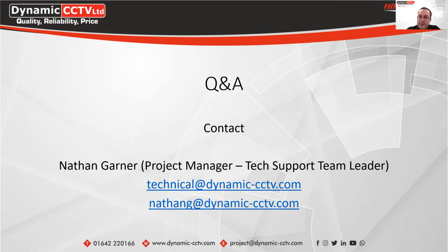Pete has asked, is there a difference in performance between TVI and network AcuSense cameras? The TVI DVR range of AcuSense technology is actually on the DVR itself. There is a limitation on the amount of channels that you can use. When you're using the IP camera AcuSense range, because it's all done on the camera itself, you're only limited by the amount of IP channels that you can add to an NVR, and you're not actually limited by the device itself. Whereas with the TVI AcuSense, on some of the units you can only have 4 channels enabled with the AcuSense alarm filtering on the actual unit itself.